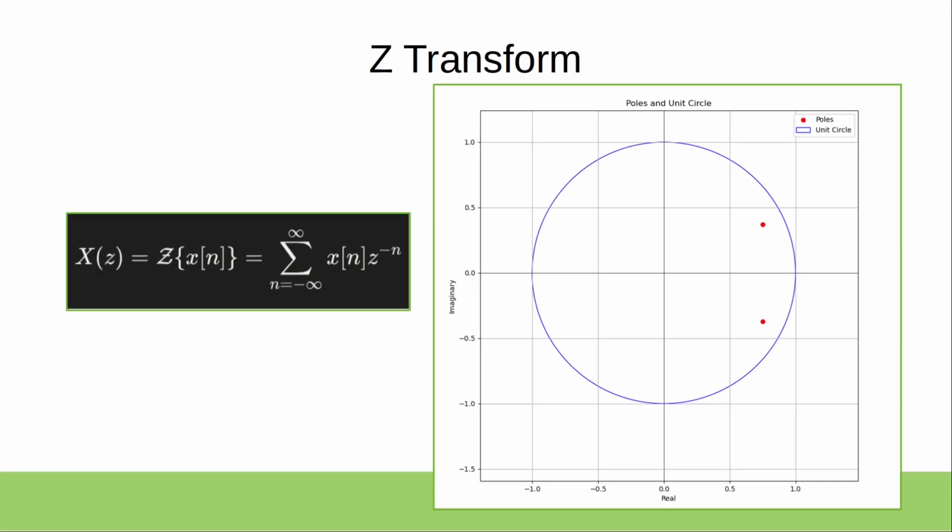But once the sampling rate becomes slower and slower, you do see more and more different dynamics prevalent, in the sense that you can even turn your system unstable when before it was stable. So this is just extra analysis that can be done after a discretization.